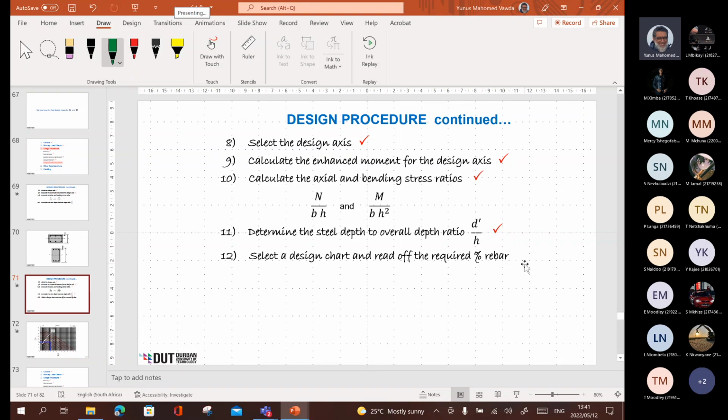So you can use that graph when you've got a grade of concrete which is different. Like Greg's done it for 30 MPa. You have 25 MPa, you have 35 MPa, you're going to have a different graph. In the old codes, they had the whole variation of graphs which were attached to the annexure. There isn't one like that now. You basically got to pick up the graph. Now, because of computers, they said you can do it yourself.